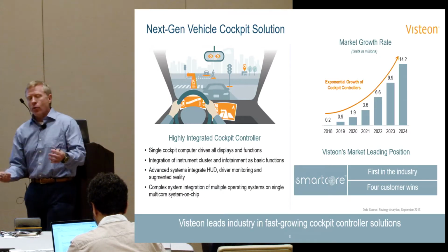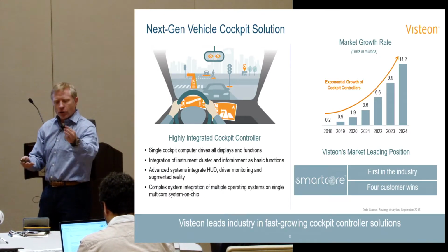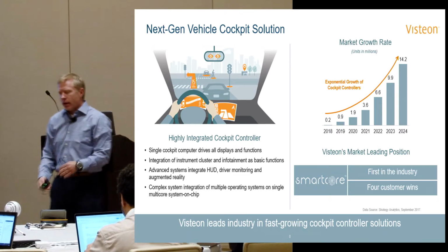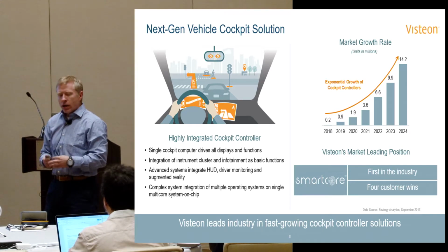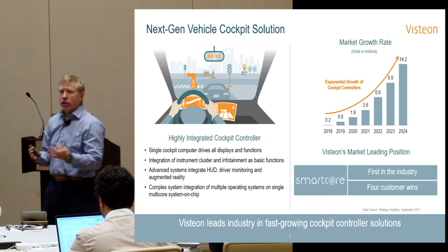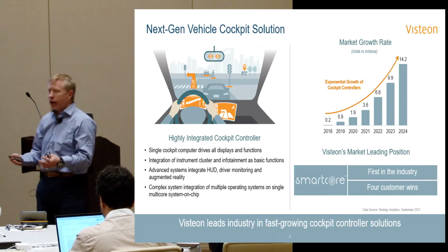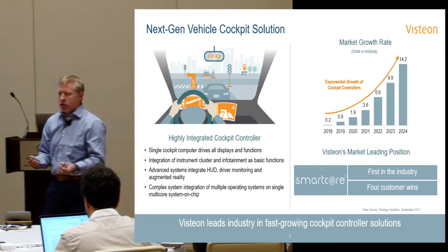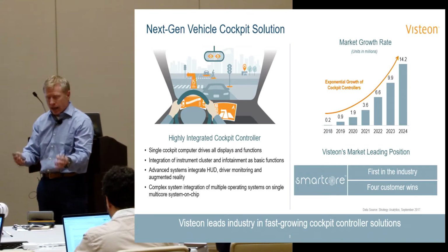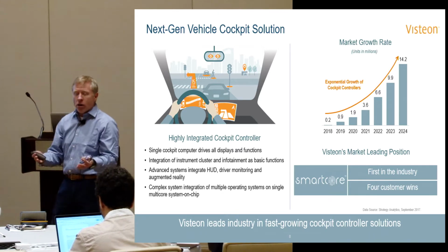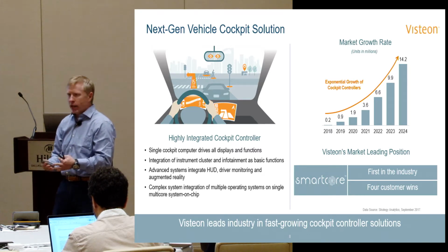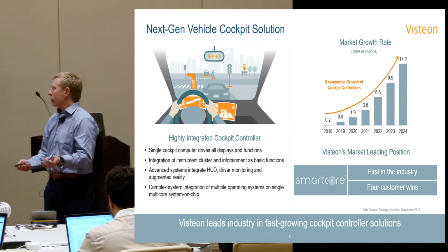And where are we going? If you recall a few slides ago, I showed the domains: instrument cluster, heads-up display, and so on. The trend is to centralize many of those domains into one controller, which will be called an integrated cockpit controller. So you'll have the cluster functionality and the infotainment functionality and the audio functionality in one centralized controller that has many cores on it, many different operating systems, hypervisors, and all the like.